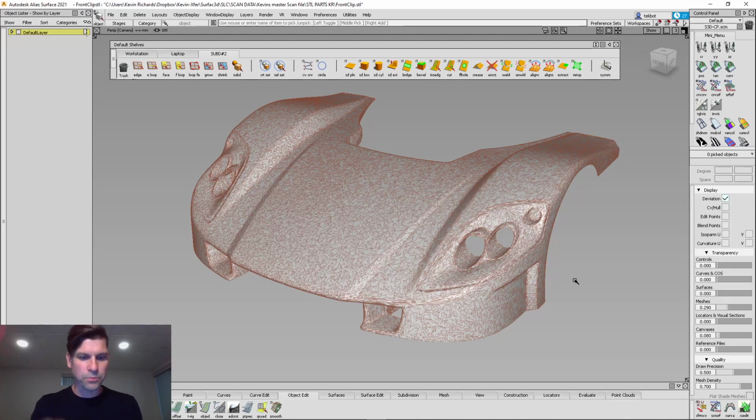And the way they have approached it is hands down the best for our type of environment, our engineering, our CAS related modeling tasks. Because you can be very precise like an engineer, and you can also have the loose, freeform organic ability like you would find in a polygon modeling tool. Polygon modeling tools don't lend themselves directly to automotive because a lot of times we talk in terms of exact measurements. You know, give me a 5mm radius. I want a 3mm gap. Make that, you know, whatever, 100 mils over. Those things are somewhat difficult in a polygon tool.